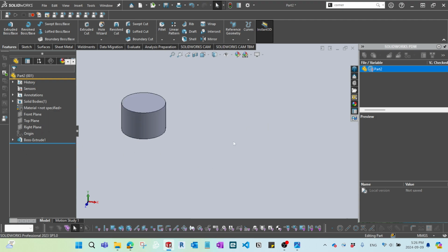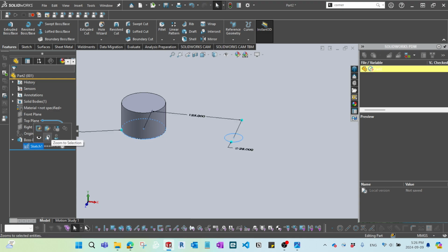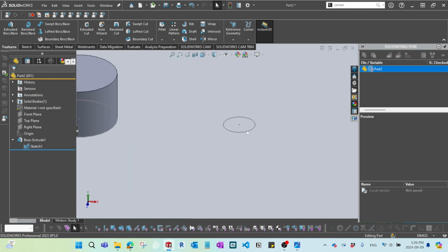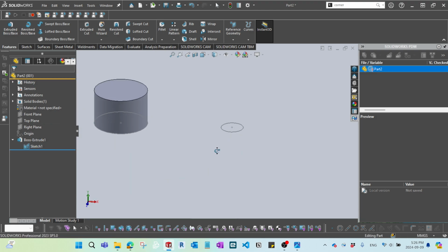you might already notice that one of the sketches in the same sketch has disappeared. The way you can make the sketch visible, the one that you used for making a feature, is you can go here and click sketch, and then you can make it show. Then you can see this bottom feature, and you can reuse it.